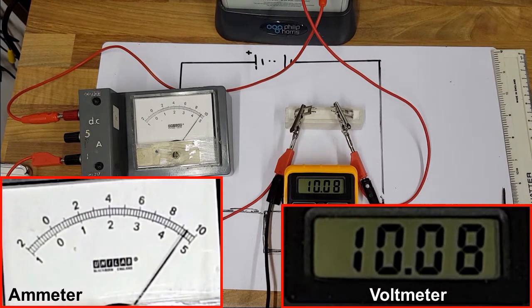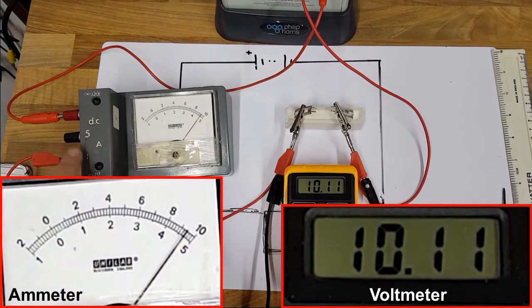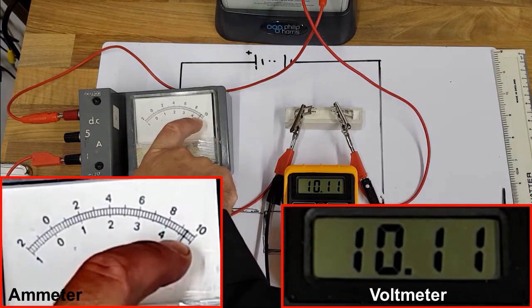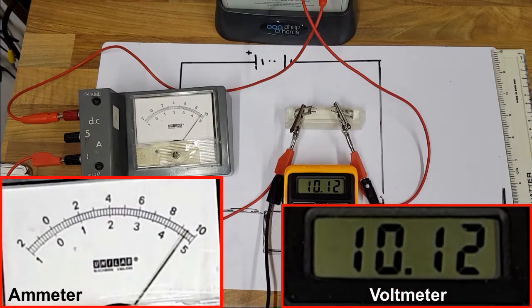Going to stop it there for just a second, just so that we can analyze what we have. On the voltmeter, you can see that we have a potential difference of about 9.5, just a little bit over. And over here, we have a current, if you remember this is from 0 to 1, so this will be a current of around 0.95-ish. So that's where we're at. The potential difference is jutting about a little bit, probably due to some internal fault with the wiring, but nevertheless, around 10 volts is around 1 amp on this.